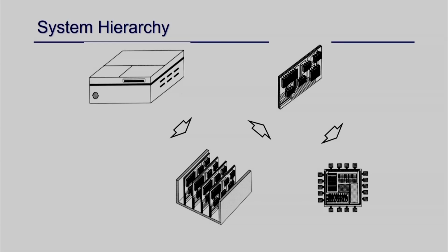In each substep, I'm just going to define the problem and discuss the issues, without going into all the existing algorithms. Okay, so we'll start with partitioning. Partitioning is something very common in every approach, right? Just think about ASIC prototyping. What we do actually is we have a big system, which might be a HAPS board, where we stack multiple FPGAs. I want to map a big processor onto an FPGA board, and it does not fit in one FPGA; it might need 100 FPGAs.